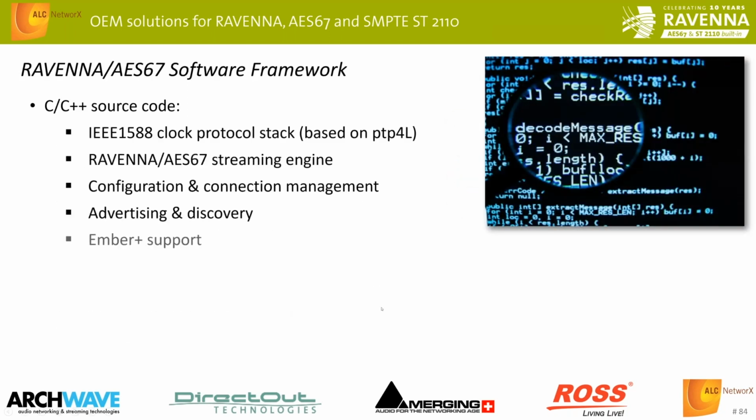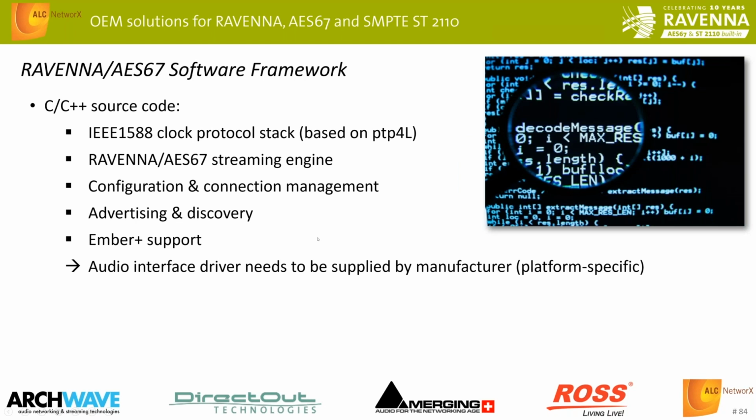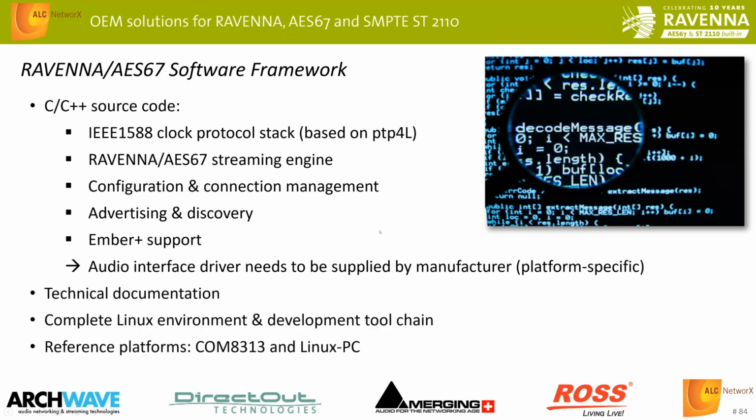The software processing framework, which is also being used in the Ravenna virtual sound card, is another option. However, for porting that onto your particular platform, you would supply a PTP client. We currently use the ptp4l, as well as a matching audio interface driver, because we just don't know what the audio interface looks like on your particular or envisioned platform. So that needs to be supplied on your side. So that is another option available from us. Of course, technical documentation and the development tool chains come with it.